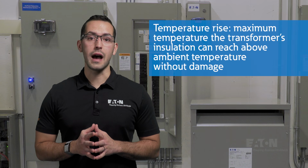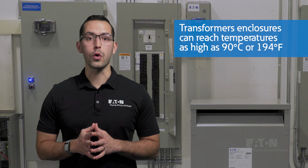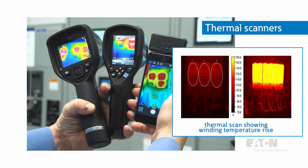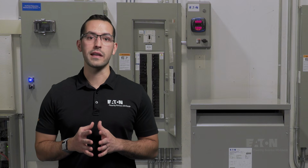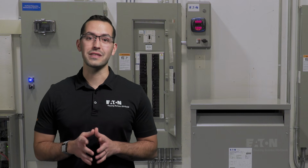Harmonized standards allow for transformer temperature enclosures to reach as high as 90 C or 194 degrees Fahrenheit. Instead of your hand, be sure to use a thermal scan to measure the enclosure temperature. Given the temperatures of these units, many customers ask if these transformers require a special fire-resistant room when installed indoors. The answer is that they do not.